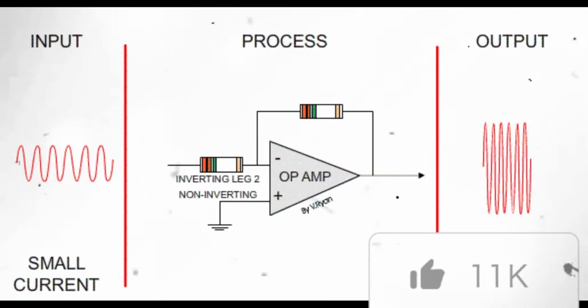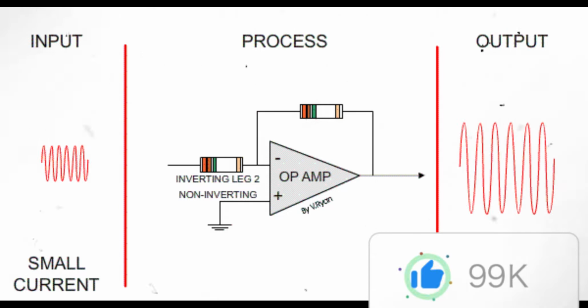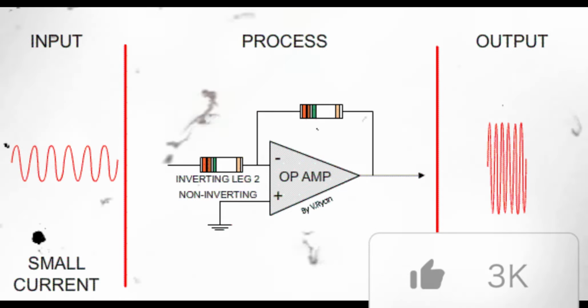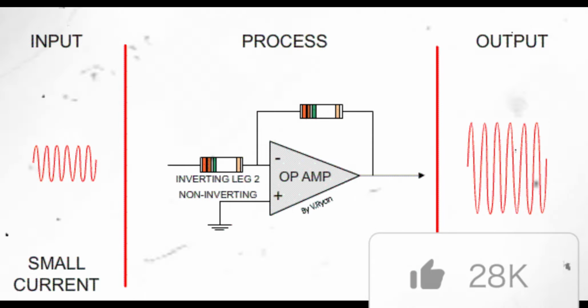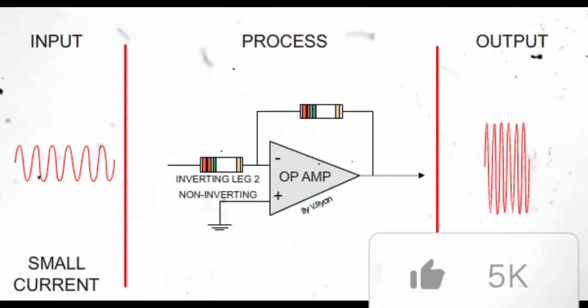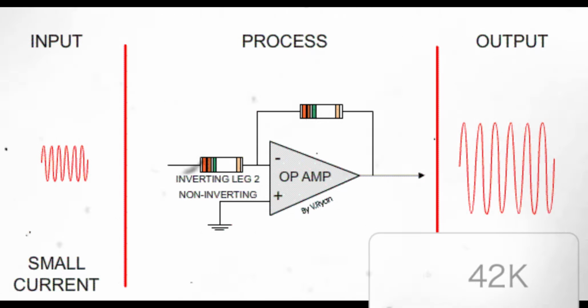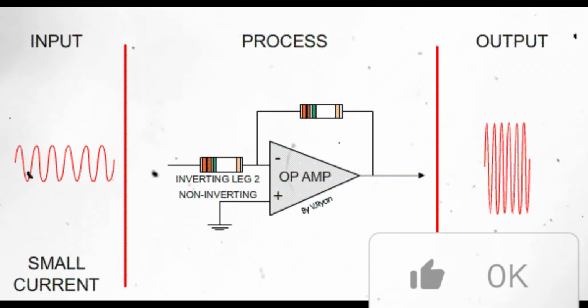By comparison, a large signal voltage gain, aka AVD, depicts the ratio of the output change to the input's differential voltage shift. It is measured at low frequency DC, and the amplifier produces a larger voltage output.